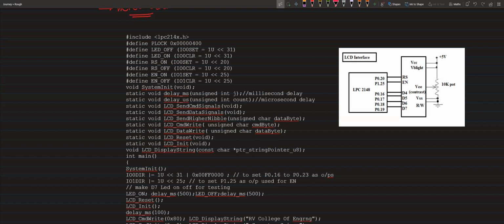And we have 4-bit data. What is the use of that 4-bit data? Sir, we are sending the actual data. Yes, it's a special case. Actually, it should be 8-bit data, but we are using only 4-bit data. That is one of the modes. By sending a particular command, we are setting the LCD into 4-bit mode. So on that end, we have seen.